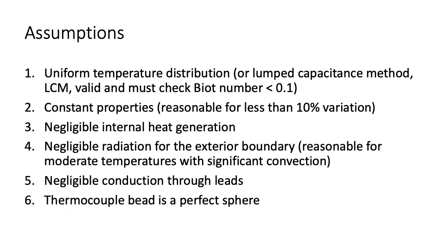Our first assumption for this problem is that the temperature within the bead is uniform at each instant in time. Use of this assumption is called the lumped capacitance method, and we will calculate the Biot number to ensure that this is a valid assumption. Our second assumption is constant properties, which is reasonable as long as the properties have less than a 10% variation over the range of conditions.